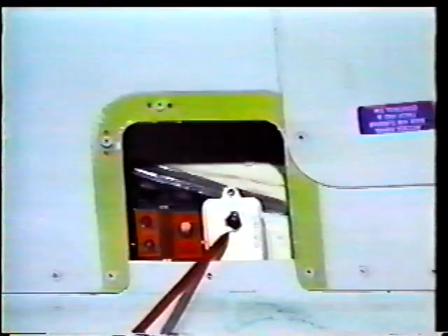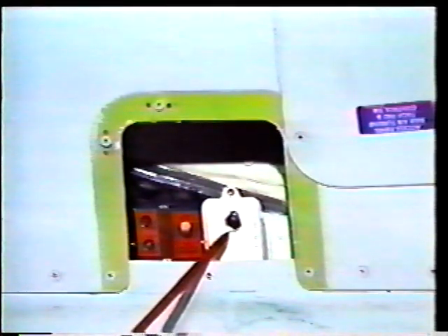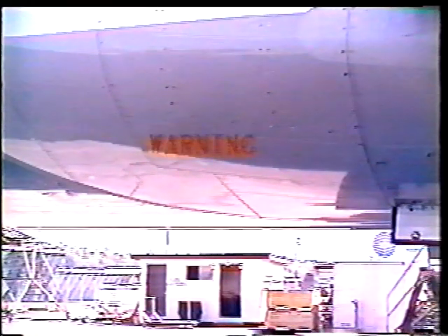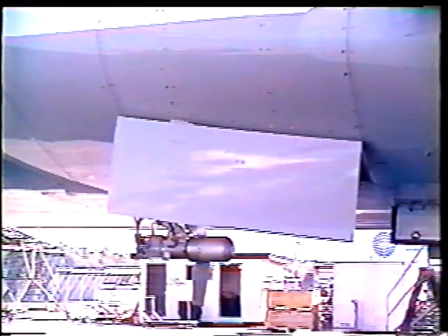The ram air turbine, or RAT, is located in the aft right body fairing. Located near the bottom aft area of the wheel well is a ground manual switch. This switch is used to deploy the RAT when the airplane is on the ground. Warning: before deploying the RAT, clear the deployment area of all personnel and equipment. Do not stand directly aft of the RAT or in its arc while deploying.